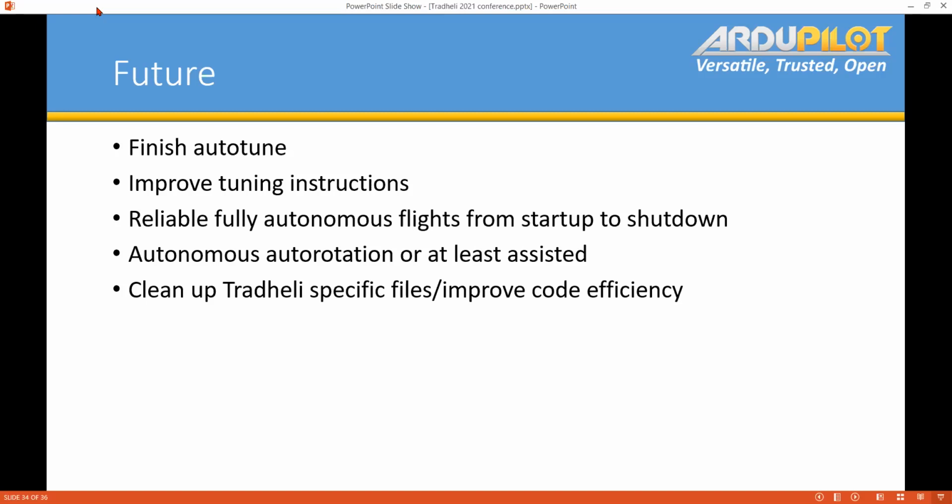Yeah, I've changed my thoughts on how we handle vibrations. Since the whole harmonic notch came about, I've worked hard to pull most of the vibration out through the harmonic notch, basically going on the 1 per rev, the N blade per rev, and the 2 N blade per rev frequencies, and that pretty much pulls a lot of the noise out of the control signal.